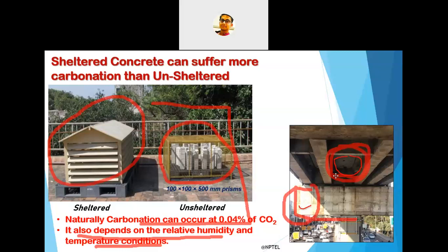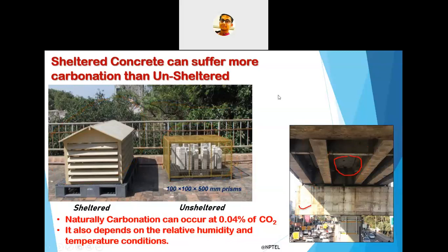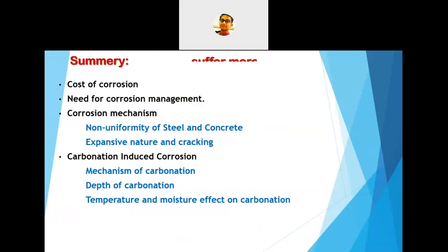So these are the things I want to share about carbonation induced corrosion. Humidity and temperature play a vital role in the initiation of carbonation and the propagation of corrosion by such mechanisms.